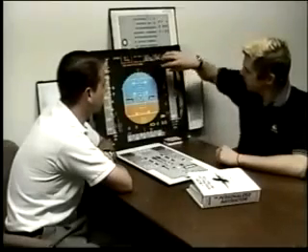What would occur on a non-precision approach? On a non-precision approach, there's a similar function. It's a VDEV. We normally get a magenta VDEV up here for an approach nav approach, but if we get a flashing amber VDEV, that indicates a similar situation. It indicates that I've selected a non-precision approach in there, but I have the ILS push button displaying the glide slope. Glide slope takes precedence over anything else, so we couldn't see the raw data for the approach.